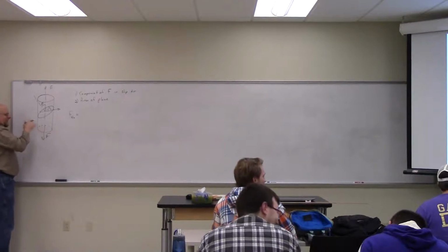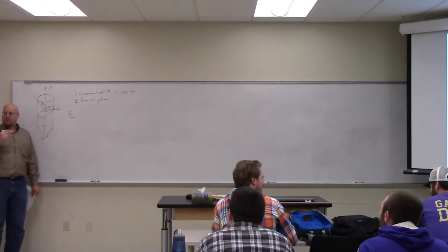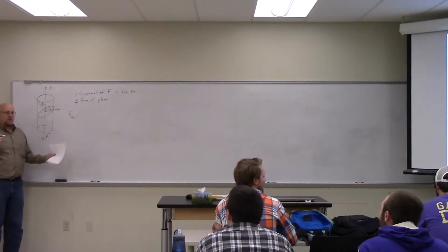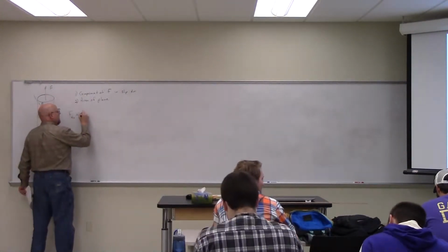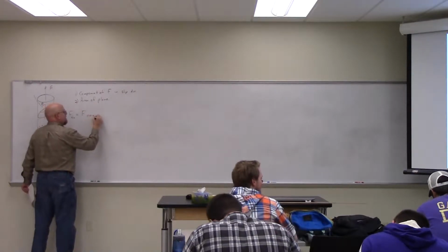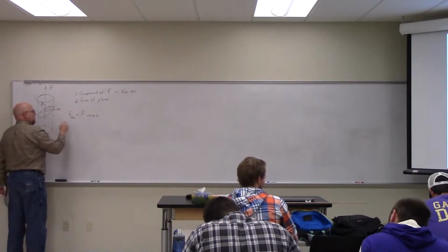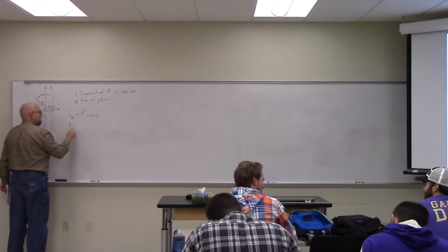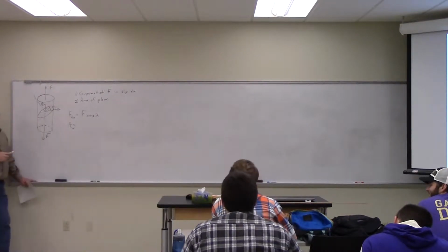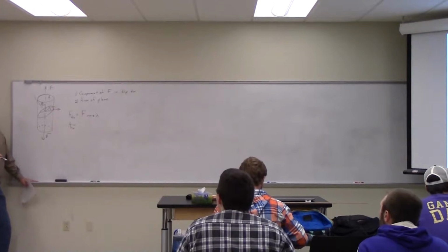All right. So what's the component of force in the slip direction causing slip? F cosine lambda. What is the area of the plane on which that slip is occurring? Let's assume the area of the end of the specimen is A. We're not worried about what the exact radius is.